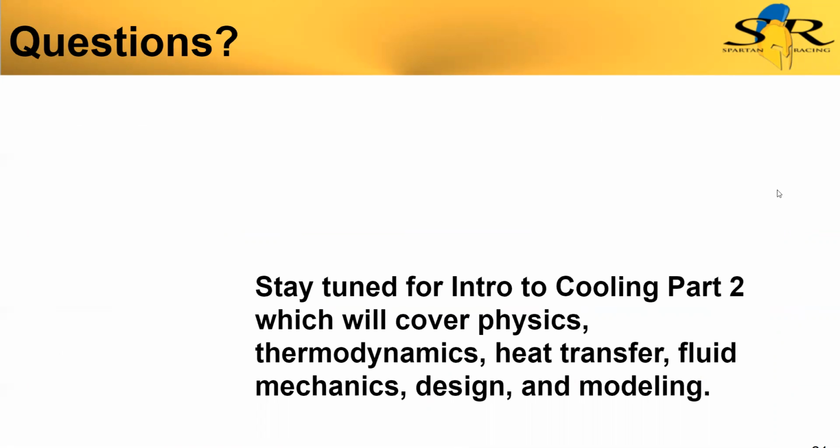Yeah. So on a cooling loop, I understand that with higher flow rates, you'll have higher pressure drops and so on. But if you have a component that can handle the least amount of pressure in your system, like its seals or whatever, you would put that at the beginning of the loop, right? Not at the very end after all the pressure drops. You would put the one with the lowest pressure handling towards the beginning of the loop, or